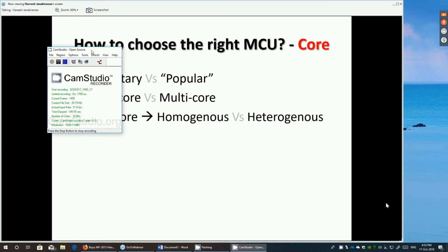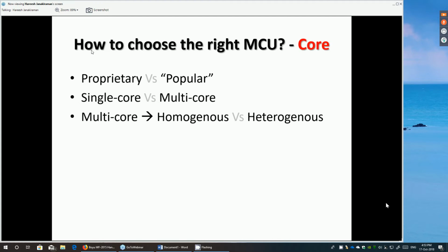There are some specific operations in signal processing, like fast Fourier transforms or implementing digital filters, where you have to multiply two parameters and add it to a different parameter in real time. So if the architecture of a chip takes several clock cycles to perform this, the operation itself may be completed, but it may not be completed in real time.